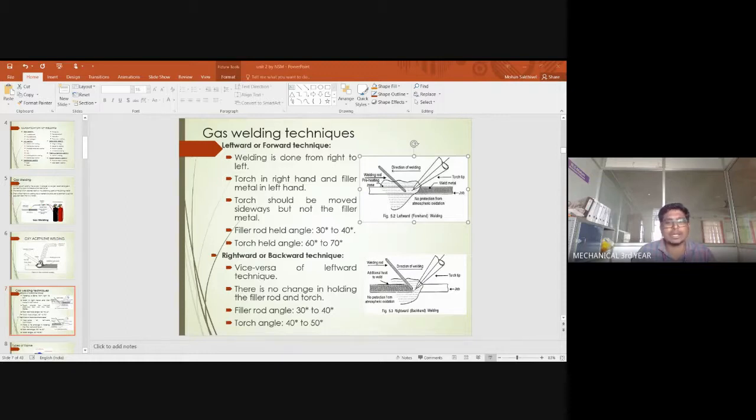So these are the inert gases that have been used in this particular TIG welding process. TIG welding is used for welding steel, aluminum, cast iron, magnesium, and stainless steel. So this much material can be joined with the help of the TIG welding process. Next, it is suitable for welding plates of thickness less than 6.5 mm. The thickness of the weldment should be less than 6.5 mm.